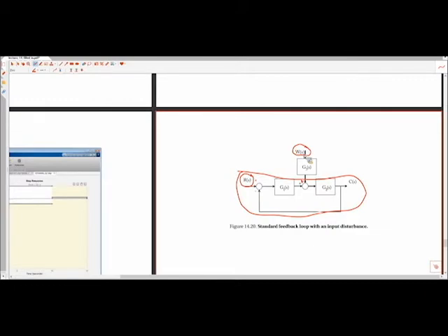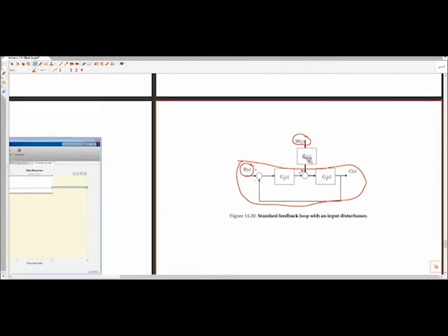You have to consider that it gives you two steady-state error requirements. One is for a change in reference, and one is for a change in mass. Right? And so you have to make sure that your controller can be robust to both of these and have an error below the specified threshold for both of them. So if we look at what is this transfer function C,